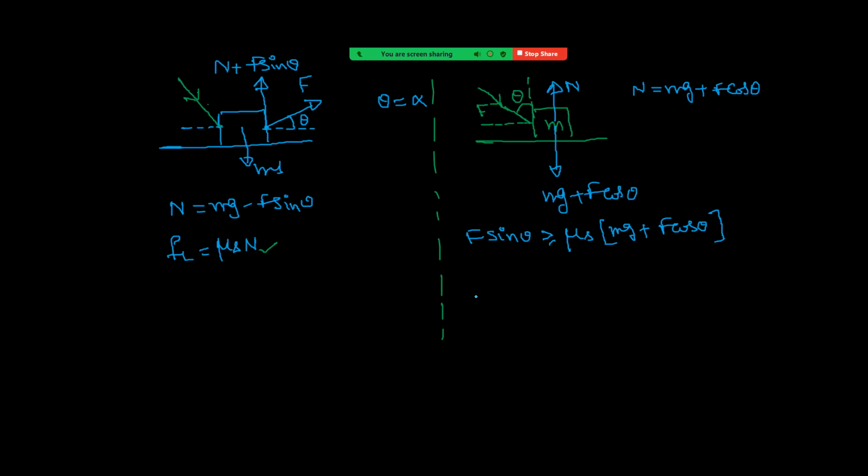Okay. Right. Now see the expression for F. F should be greater than or equal to mu s mg upon sin theta minus mu s cos theta.